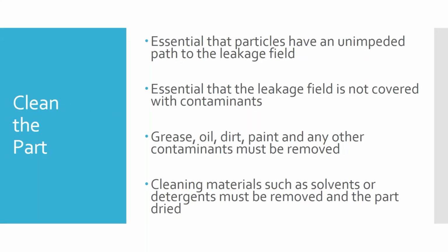And so you'll typically use cleaning materials such as solvents or detergents. So we've got the cleaning tanks that have the mineral spirits in them that you can use. I've got alcohol, isopropyl alcohol is another good one that dissolves oils and greases and that kind of thing. But then the part needs to be fully dried. Why is that?